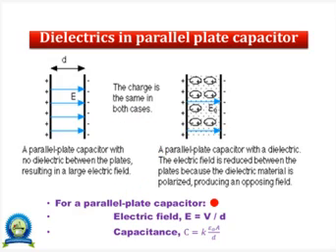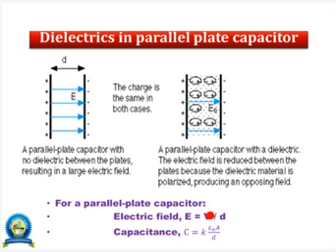Okay? Now, for parallel plate capacitor, electric field is usually computed or calculated as the ratio of applied voltage divided by the distance separating the plates. Now, let me quickly say this. Field will not be set up within the plate except there is an applied voltage. Is that okay? And the field that will be set up will be the ratio of the applied voltage divided by the distance, and it will have a unit of volts per meter. Volts per meter. That's the unit of the electric field.